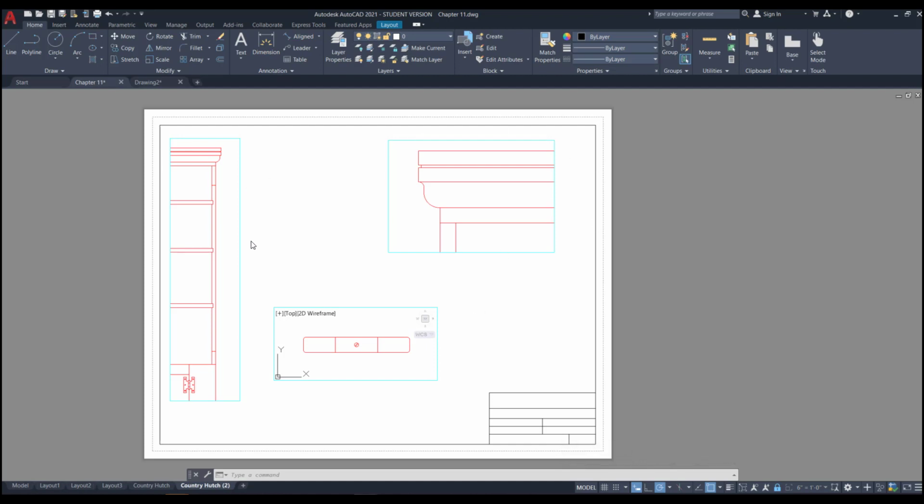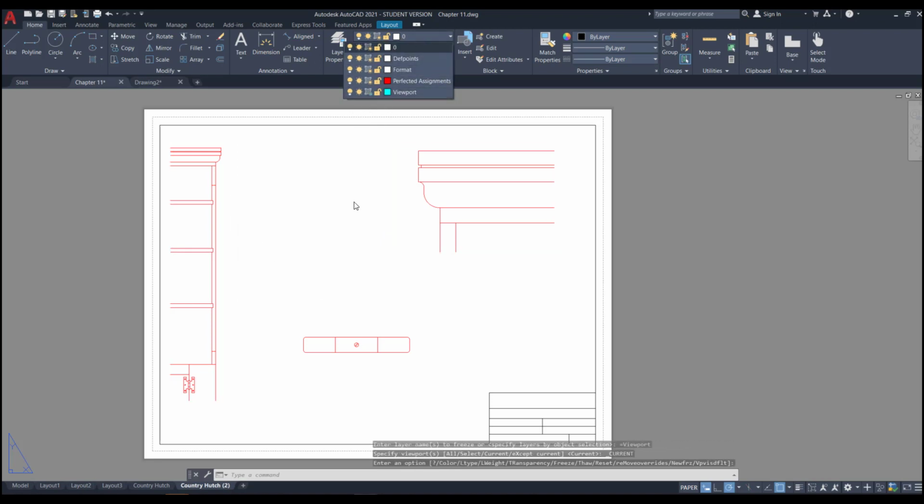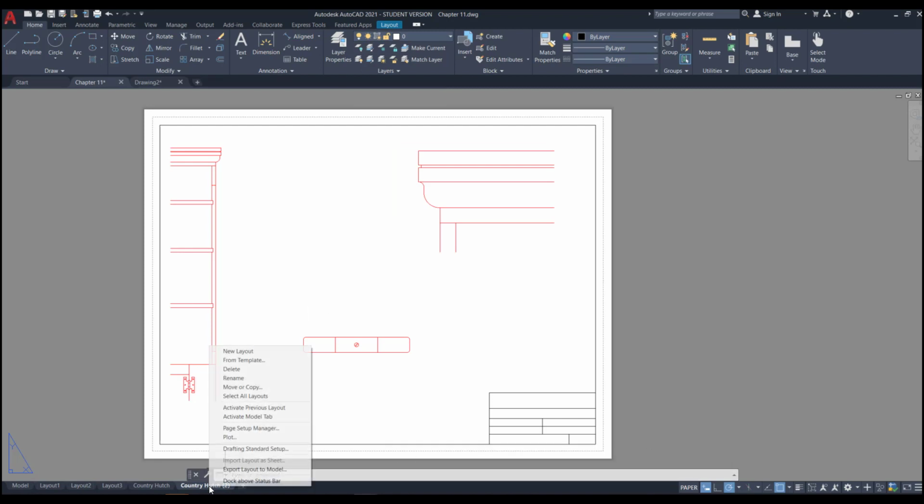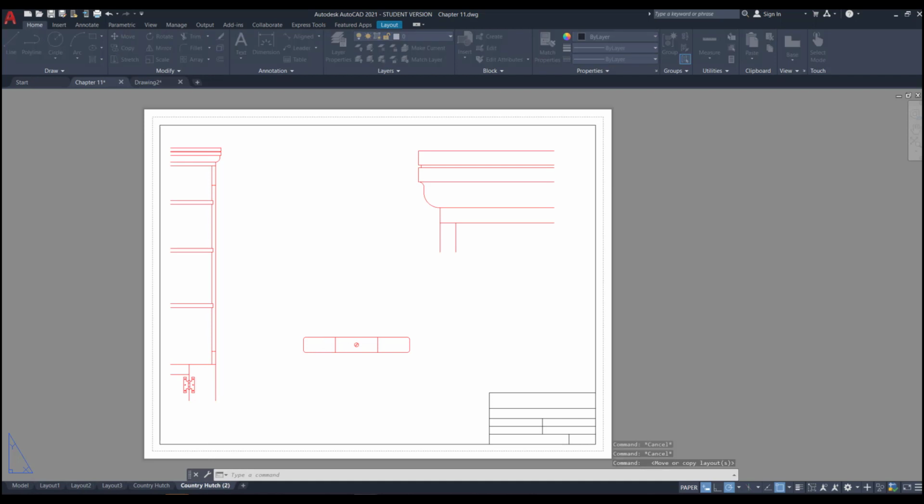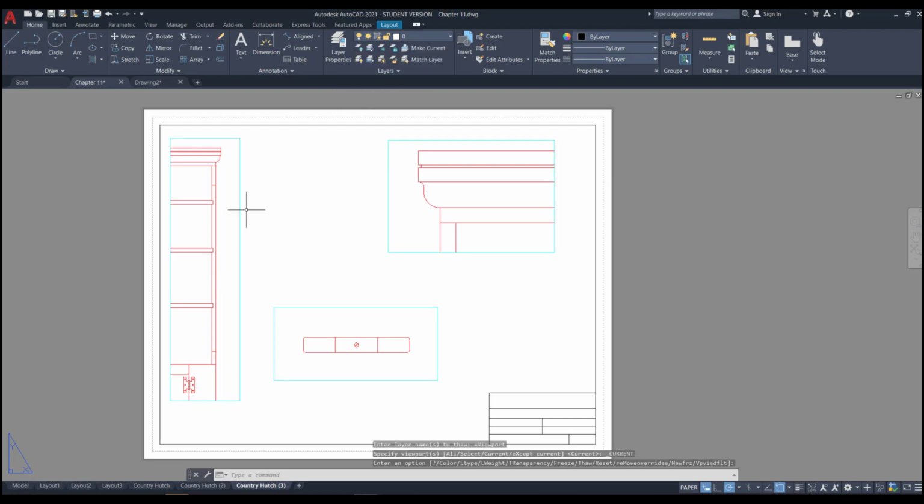Okay, and now I'm going to just freeze the viewports, okay? So none of them should be activated when you freeze the viewports, okay? And the same is again for the next one, okay? Create a copy of this one. Move it to the end. Go to the, and then zoom on the portion that you want. So make it visible.